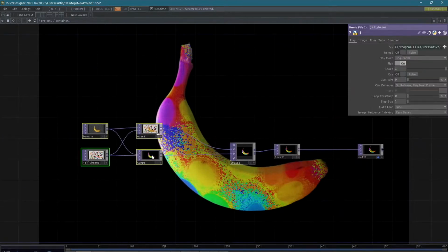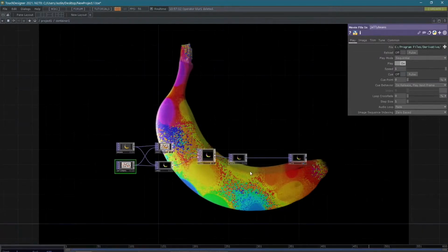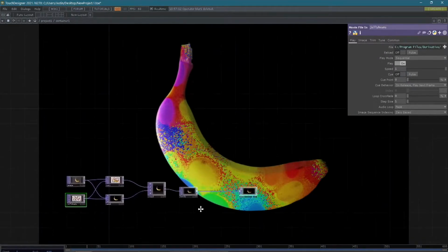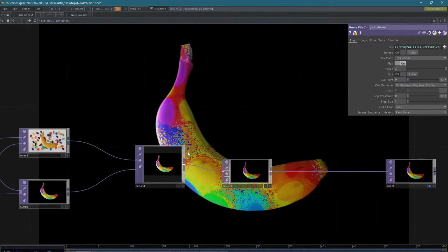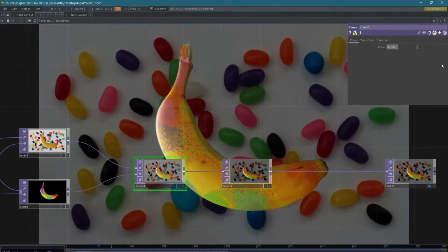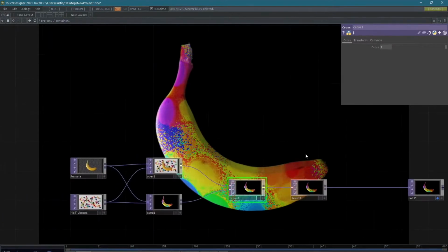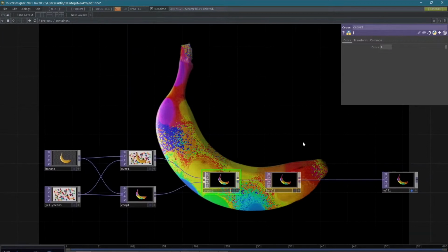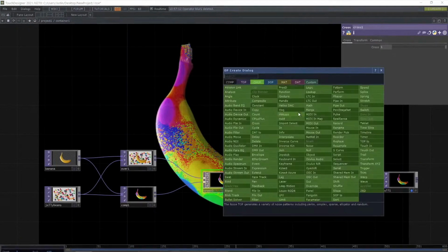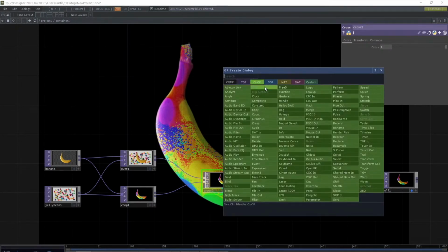So we've got a little basic graphics workflow. It's nothing fancy, obviously. Just right-clicking, rearranging, cleaning things up, and scrolling out so I can pull it out of the way. So we can, of course, click through and just use these parameters in here to control things, but it's kind of cumbersome. So what I wanted to do is start automating parameters or doing something automatically. So I'm going to hit tab, and we're going to hit tab again to switch over to the chop menu, and you can also just click these, just like tabs.